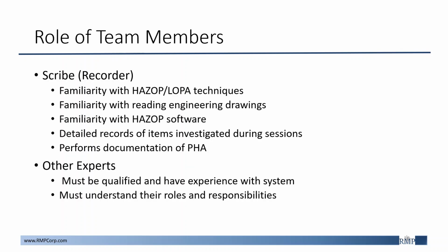The facilitator can also be tasked with both facilitation and scribing duties depending on various parameters of the HAZOP, such as system complexity, team composition, and the size of the team. The pivotal decision-making parameter for the inclusion of a scribe is whether the additional cost of a scribe outweighs the money saved by shortening the HAZOP sessions and the subsequent documentation time.